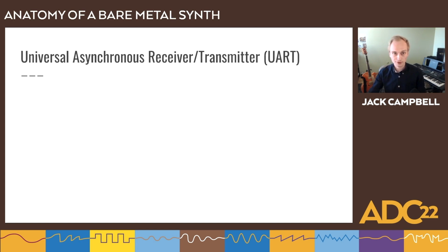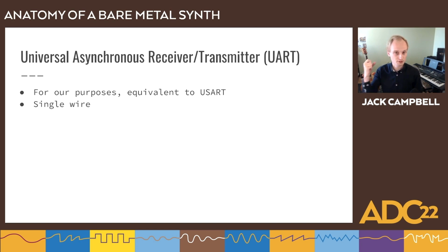The next one I want to talk about, bringing us back to MIDI, is UART, or you may also see, if you continue watching the talk, USART, which is Universal Synchronous Asynchronous Receiver Transmitter. The difference doesn't really matter for our purposes. All we need to know is that it's 1 wire, and then we don't have a clock line like we had with I2C.